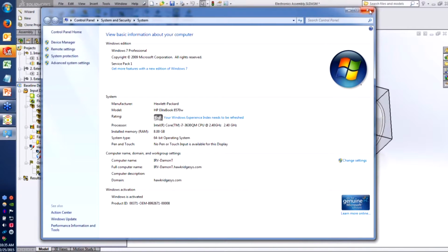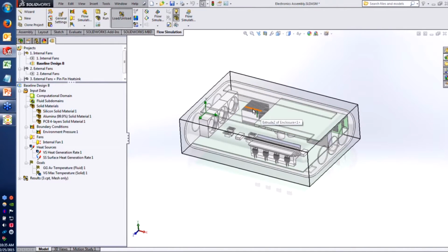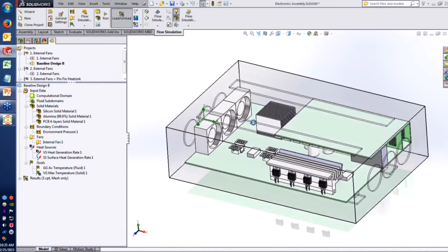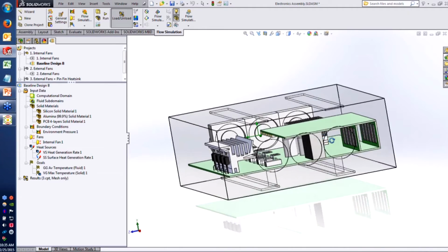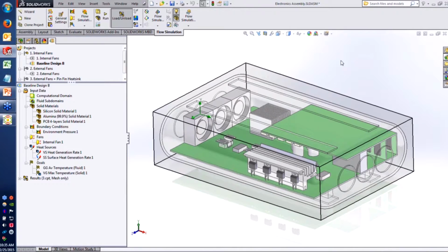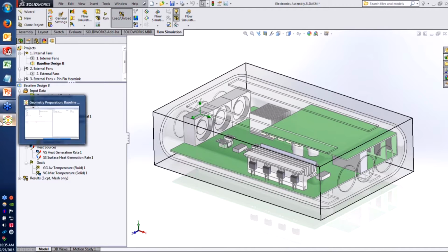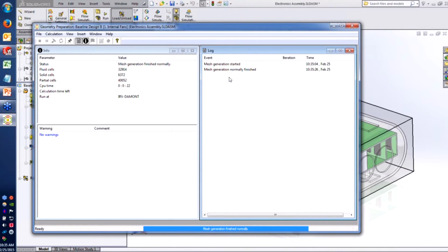Whereas here, I'm going to only be in about the 150,000 cell range, so nowhere near the limits of what you would be able to do as far as detail in the geometry. And that's usually important for these electronics cooling applications because there is so much more detail that you have to worry about with all the different chips and components on your PCBs and the complex housing that it might be in. There might be a lot of narrow channels in different areas.